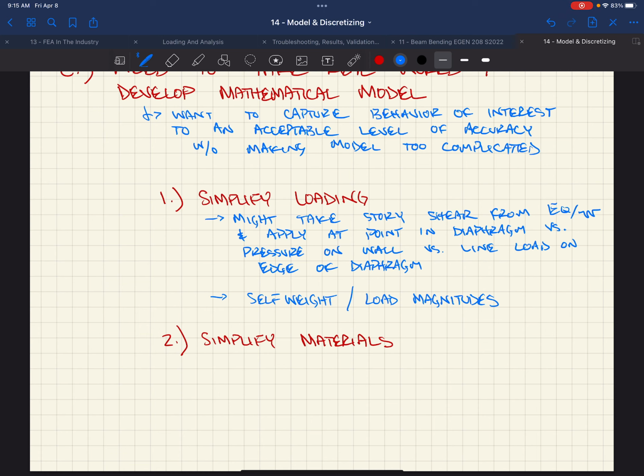But just regular brick or panels or rock or anything that gets clad on there, is it typical to run an analysis for every different kind that you do? When you do generic brick veneer and stuff like that, that goes back to an architect, who usually specifies, other than ledger angles to hold the brick up vertically. Usually those are still proprietary clips, right?